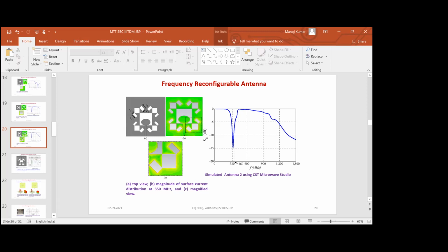In the millimeter wave, the transmission lines are in chip form. We cannot see many components with the naked eye in the millimeter range. We need a microscope to see the line. And obviously we cannot use the same materials. There is thin film technology, semiconductor fabrication technology, where they fabricate the antennas for these reconfigurable antennas. They can do it for us. We cannot do it ourselves because we cannot see those lines with the naked eye. In the millimeter range, if you are able to see your line, that means it's not good.